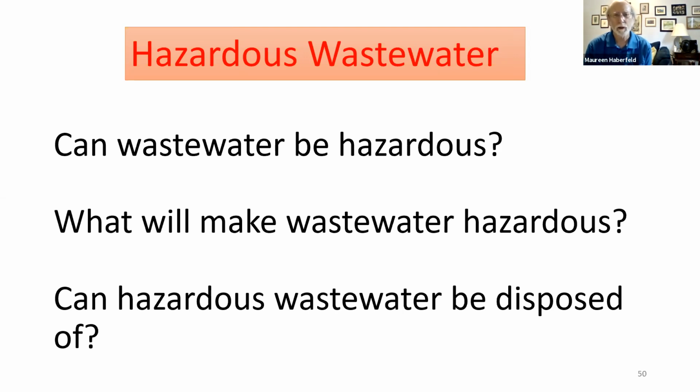But can hazardous wastewater be disposed of? Not in our state. It would first have to be treated to be non-hazardous. They'd have to do something to remove whatever hazardous constituent it had. If it had lead, they'd have to remove the lead. If it had a low pH, they would have to raise the pH and so on. Then it could be disposed of.